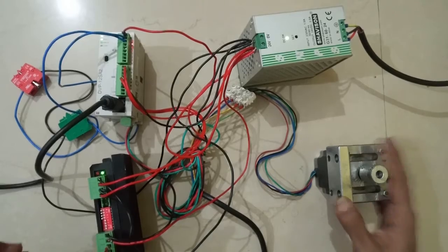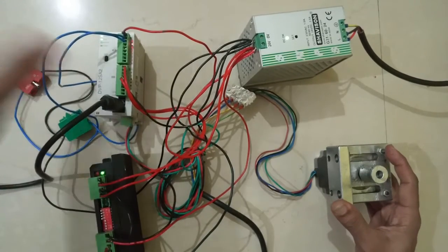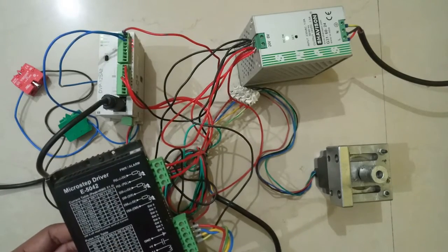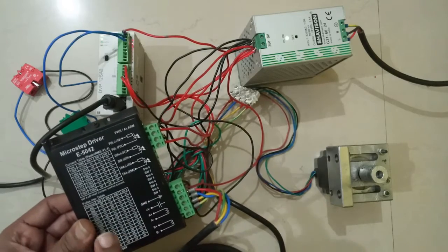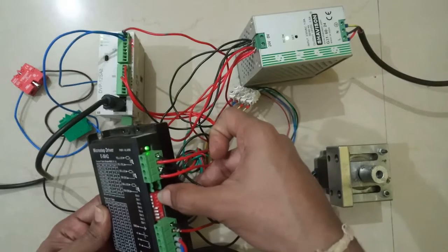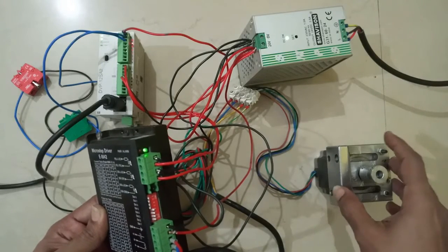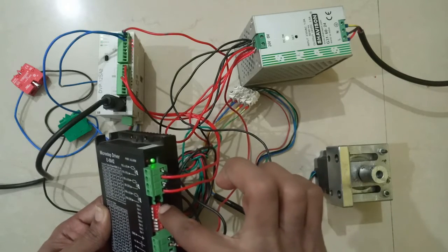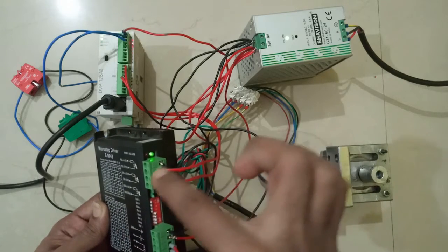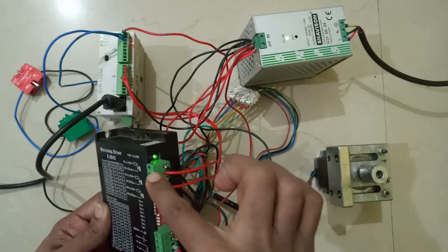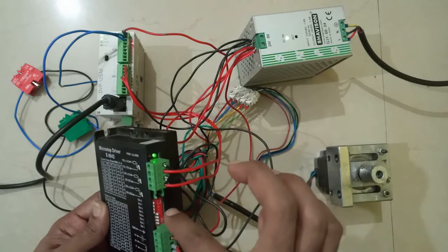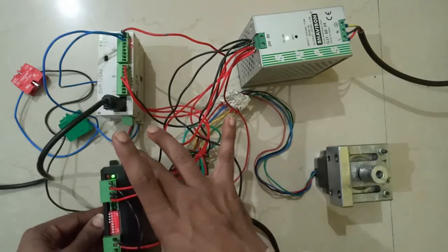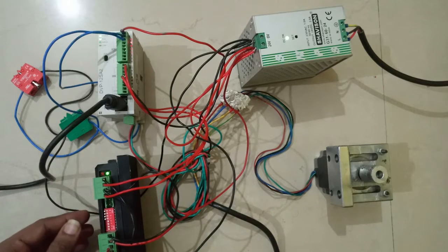You can change the speed of this motor by the program itself, which is written in this PLC, or otherwise you can just change the PPR, that is pulse per revolution. Now here you can see a table is given where you can set these switches and set the speed of this motor. Okay, but when you change these settings, you need to turn this stepper drive off and then switch it on again. Otherwise the system setting you have done will not be applied. So I'll just change the program to change the speed of this motor.